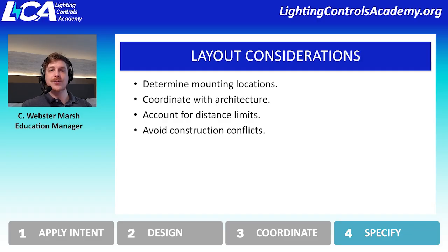And then finally, you can avoid construction conflicts. So if you're planning on putting an occupancy sensor in a tiled ceiling, the tile that you select might actually have an HVAC diffuser or return on it, which will actually cause false activations of that sensor if it's mounted right on it or adjacent to it.